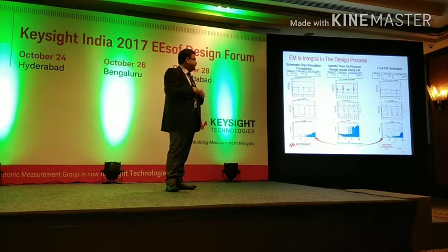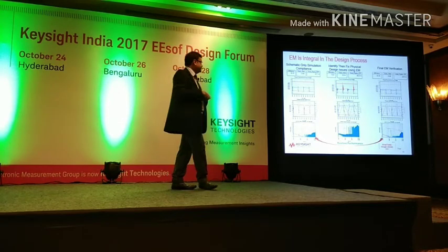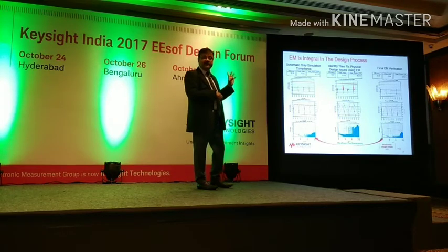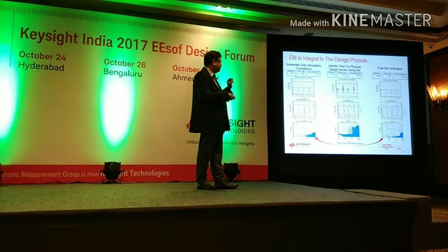So here is one test case study which I'm going to present very quickly. When you do schematic only simulation, these are the waveforms. As you can see, it's kind of clean. You are below your breakdown voltage. The gate drive looks okay. The spurious emission looks okay. So that's what was obtained in a schematic design. It's a customer test case study, actual power converter.